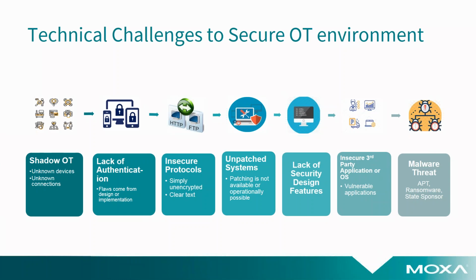Richard also mentioned insecure protocols. I think Modbus is one of the more common ones that's out there. When that protocol was designed, security wasn't really a top-of-mind issue. So the protocol itself does not have security features built into it. That can cause a vulnerability there.